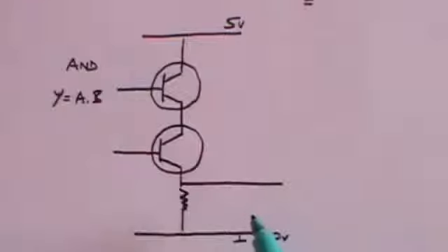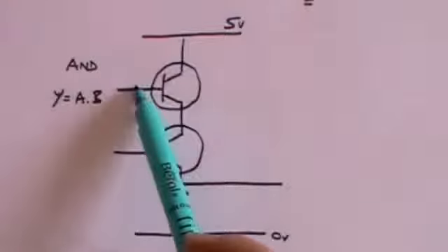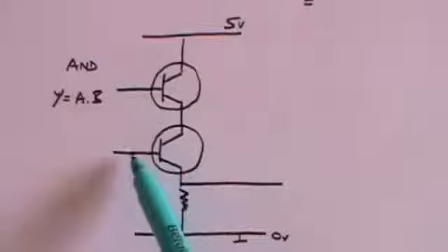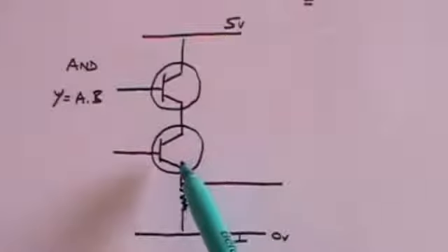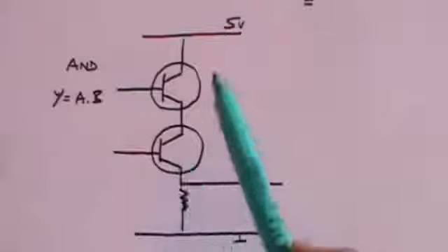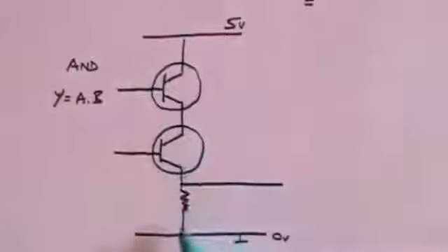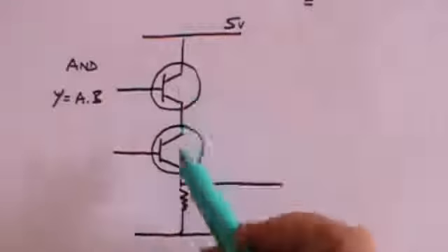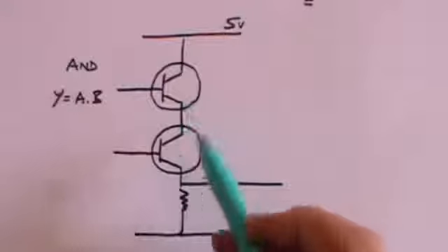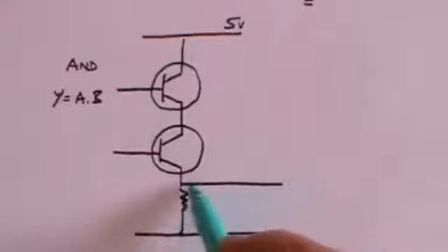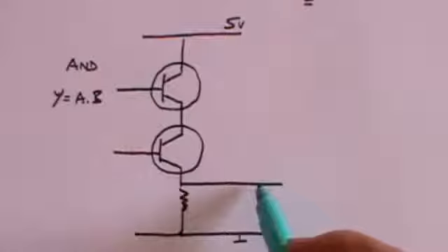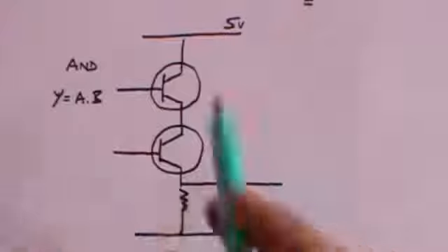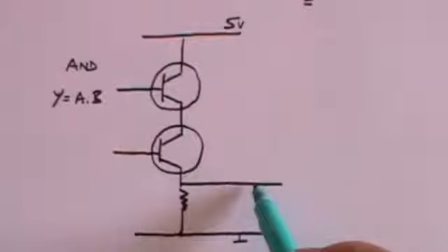What we're now going to look at is the logic. If you have no volts at all on these two inputs, then these two transistors, which are acting as switches, will be open. So no current will flow through the transistors. And consequently, since this point here is at 0 volts, then everything up to here will be 0 volts. This is essentially a switch that's open. No current can flow this way. And so all of this is going to be at 0 volts. So the output will be 0. So if the two inputs are 0, the output is 0.